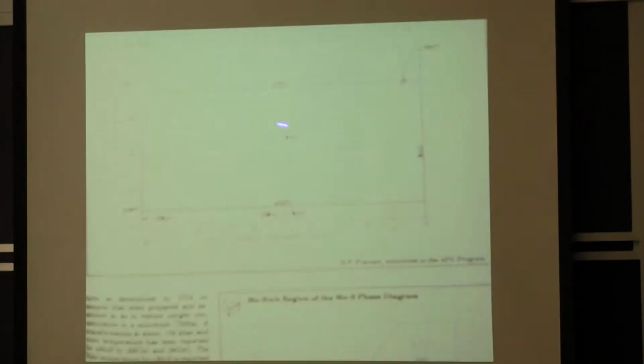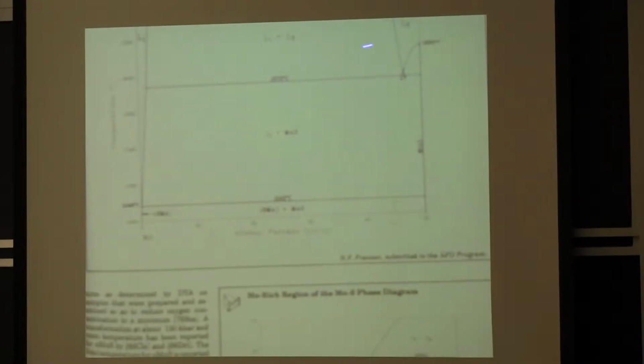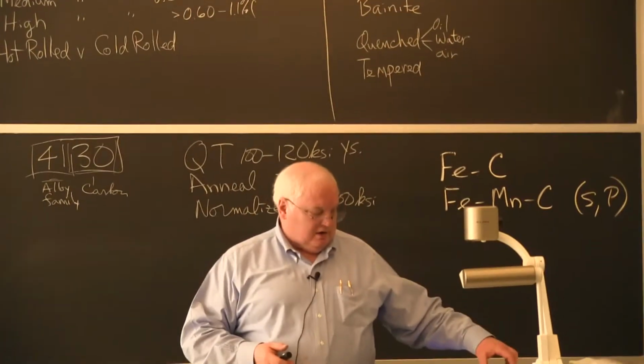So the phase diagram is such that for manganese and sulfur, right here there's a eutectic. There's two liquids that form at very high temperatures in the manganese sulfur system, and the sulfur-rich liquid, which is basically a manganese sulfide, forms a eutectic and melts at 1570 C. That means it's solid in the liquid steel because the steel melts at 1538.